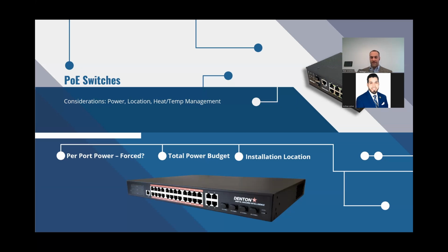There is also this 8-port switch. Now, this 8-port switch is specifically designed to be in a hot environment. So this could go in a ceiling box or an unventilated box. And it's got 8 ports and 2 fiber ports in. And it as well is designed for 90 watts on all 8 ports. So you get 720 watts out of it.